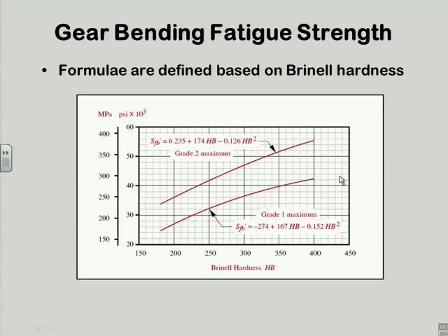I think it's primarily steel, is to take the Brinell hardness number and multiply by 500. And that gives you the ultimate tensile strength, I think, in kpsi. Check me on that in Chapter 2. I'm not certain of my memory on the units.